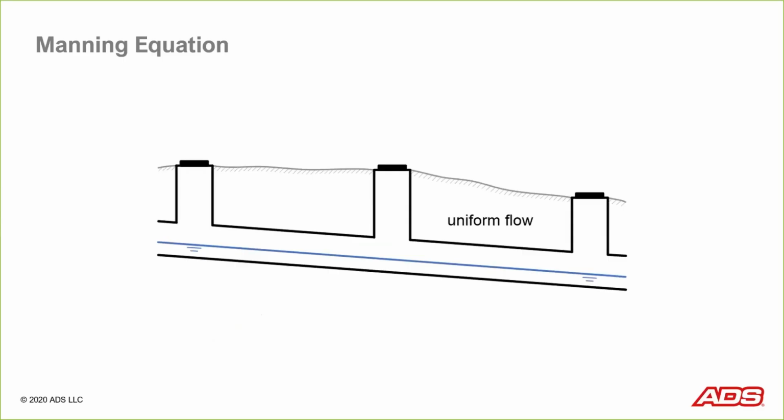So when you have uniform flow conditions, the Manning equation in its traditional sense applies. And you can think about that equation and the graphing of that equation equating to this physical condition actually going on in a pipe. I find one of the things that helps people when we're looking at scattergraphs of flow monitor data is if you can picture what that data looks like from a side profile in a pipe. Based on what you're seeing on a graph, you're going to have a good fundamental understanding of what's going on in that pipe.